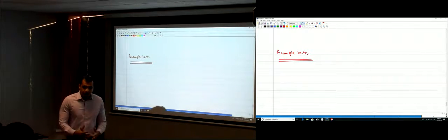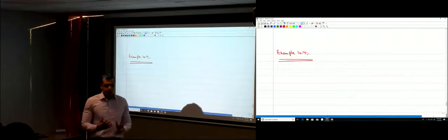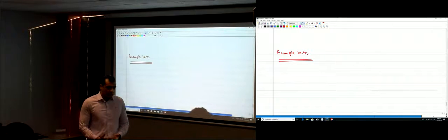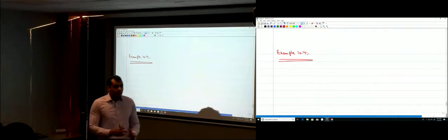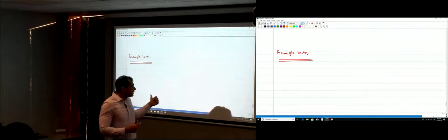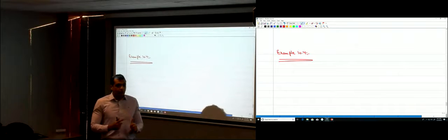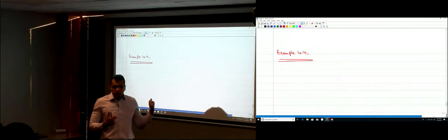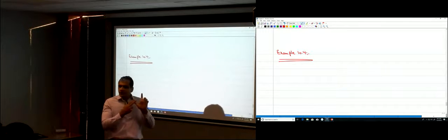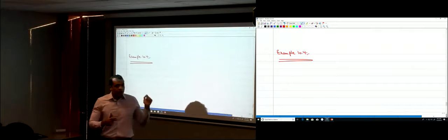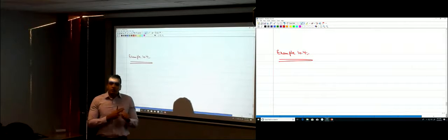When you design a beam, what were the 3 options for the problem for me to give to you for a design? You remember in chapter 4? Dimensions or area steel. So there were 3 things. We already covered one of them in example 10.3. I gave you the dimensions, and I require you to find area steel. You have 2 unknowns: the dimensions and the steel, right? In the previous example 10.3, I gave you the dimensions, and I'm requiring you to find the area steel.